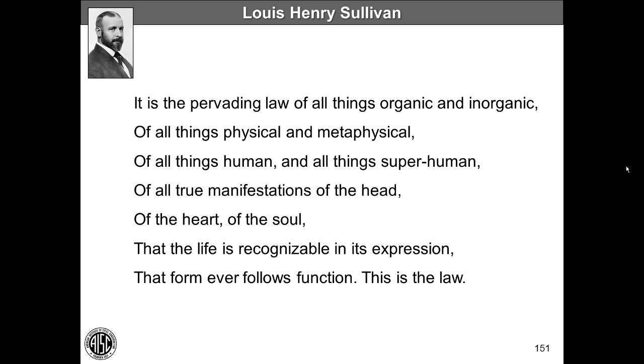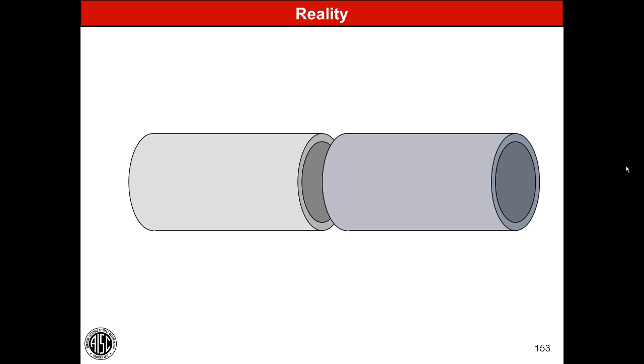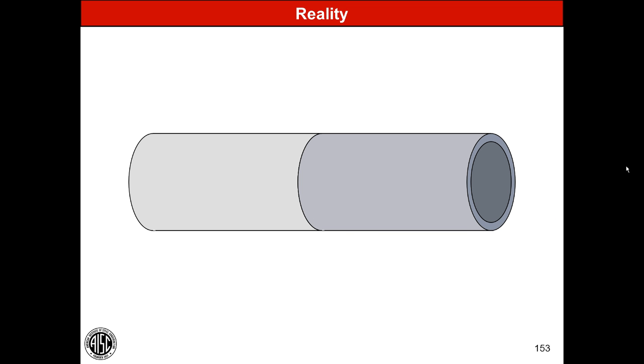I went to a hollow structural shape here, and I guess the ideal configuration would be no joint at all. Reality says we're probably going to have a joint someplace. And I'd like to suggest that directly welded, that connection is as close to ideal as you can get. And maybe you won't agree with that, but at least that's true in my mind.